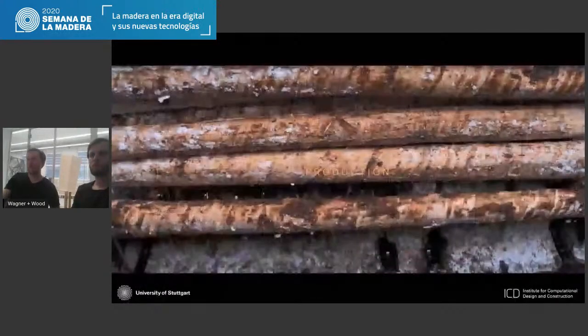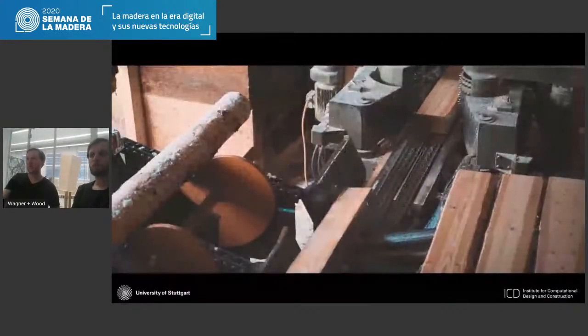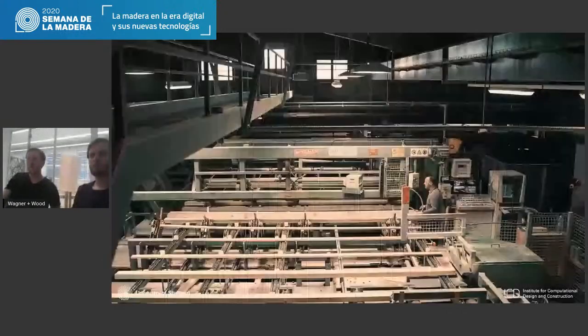Production begins then really at the heart of the material in the sawmill, with the selection of the proper board thickness that's needed for the self-shaping. This is the most important criteria of the process, where we need to sort by moisture content, something that's already read in the factory but is not usually taken into account with this much detail.